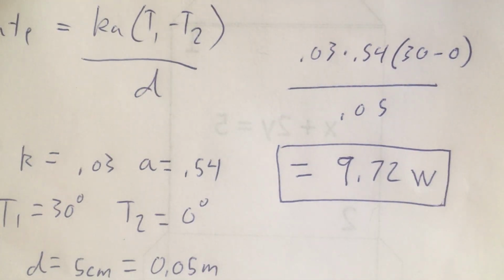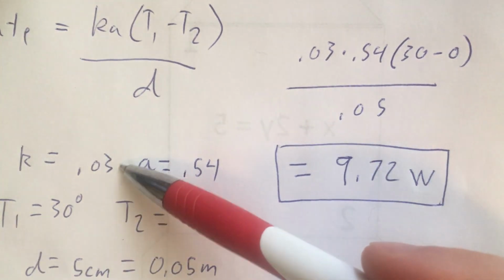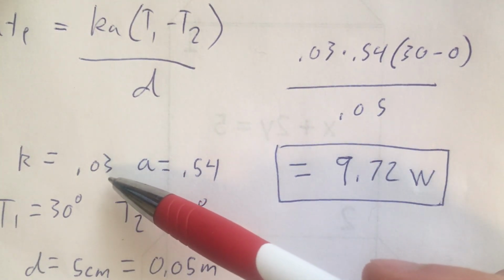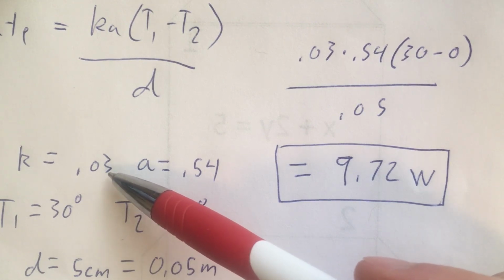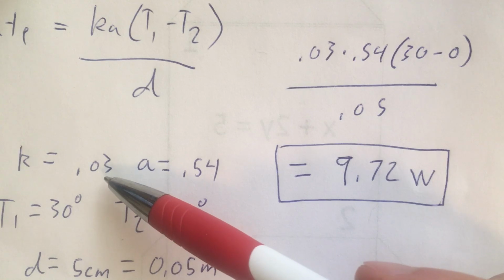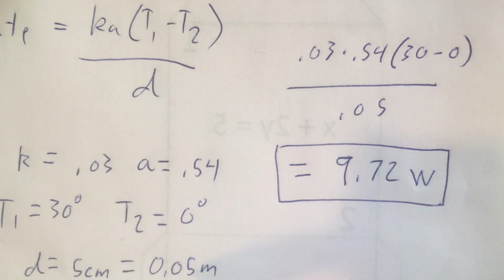So here's the thing that you should be keying into. One, we would expect this value to be lower because it seems way more insulating. But why? What is driving this equation to make it way more insulating? So there are really two things that I can point to that are going to matter a lot. One, the thermal conductivity is way lower, significantly lower, less than one tenth the value of glass, which is why we use styrofoam and we don't have glass coolers or metal coolers. That would be dumb.